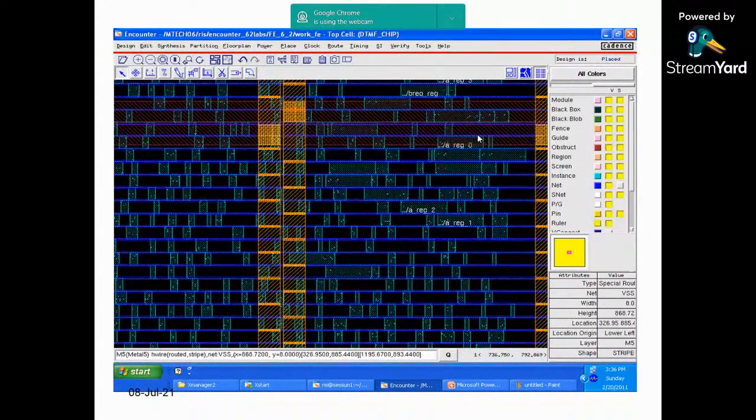You can see the height of the cells, the green color, right? All are logic cells. Either it can be a gate, a flip-flop, a counter or shift register, or even small blocks like a multiplexer, whatever. Height of the cell is standard, and width of the cell varies. Can you see the width of the cell varying everywhere? The width can vary, but the height is the same. That's why we call them standard cells. And all the standard cells are placed within VDD and VSS. Two blue lines, right? Everywhere you can see two blue lines. The cells are placed within the blue lines.